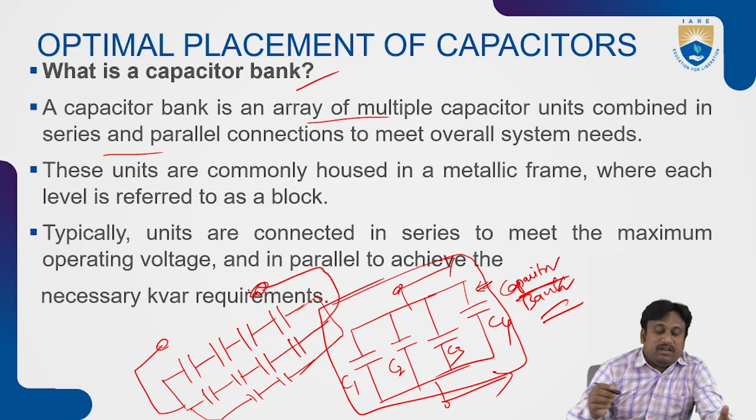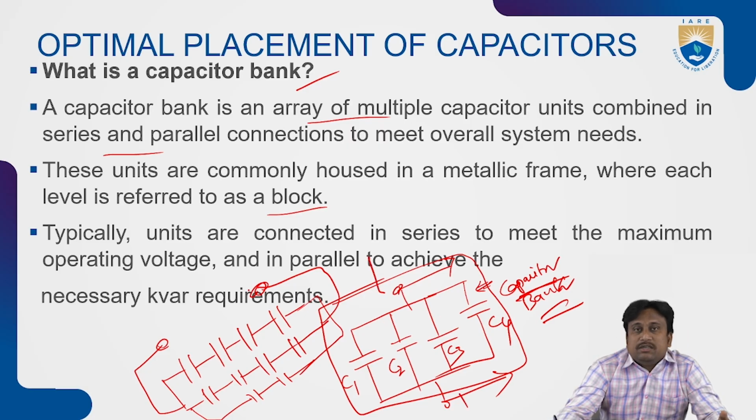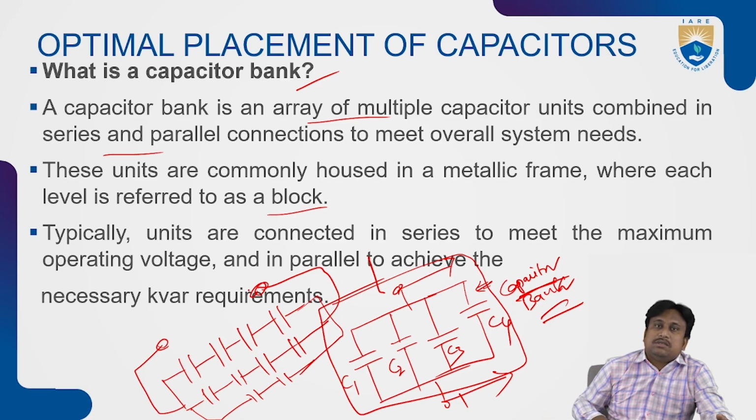Each level is referred to as one block, so we can have a number of blocks of capacitors. Typically units are connected in series to meet the maximum operating voltage, and in parallel to achieve the necessary kVAR requirements. This is usually preferred. So that is the requirement of the capacitor case.